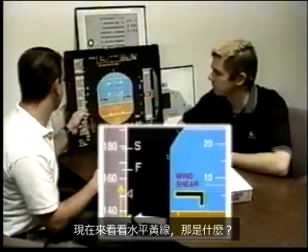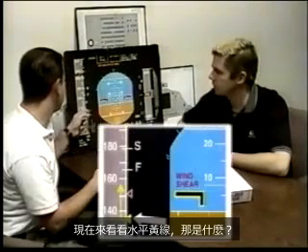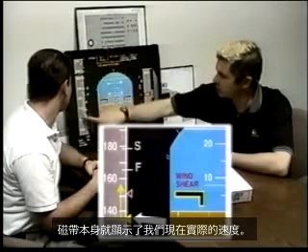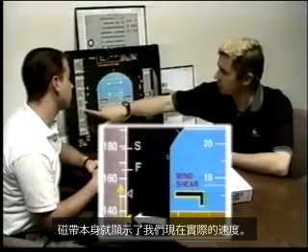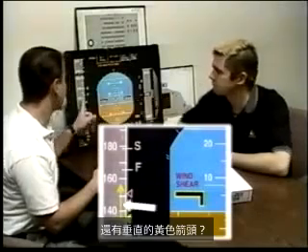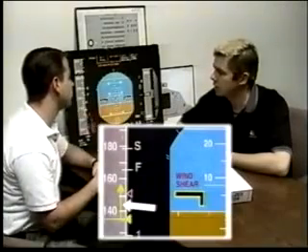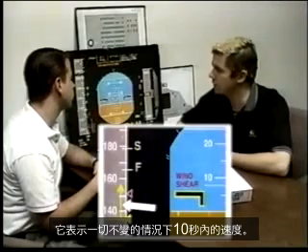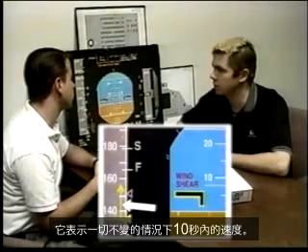Okay. Down to the horizontal yellow line. What is that? That indicates on the tape itself the speed that we're actually doing right now. And the vertical yellow arrow? That's called our speed trend arrow. It indicates the speed that will be in 10 seconds if everything remains constant.